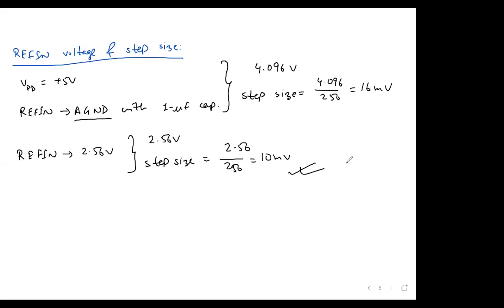The difficult thing is that you need to know the pins. Understanding the description and connection is all easy, but you need to remember the pin configuration, which ADC contains how many pins and all these things. That is the difficult task. But other than that, if you just understand this once, it is very easy. There is nothing different or difficult. The only difference in Max 112 is that since it is serial input output, you need to design it based on the serial clock. So pay attention to the question which is given.